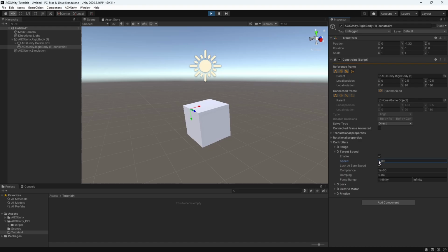You would like to control the speed, and then when you set it to 0, you want it to stand still, perfectly still. And if we would make this default stiffness again, we can start the motor, and then if we set the speed to 0, it will be perfectly still and it will hold this position forever, because now it's a positional constraint instead of a velocity constraint. So this can be very useful simulating cranes and things like that.